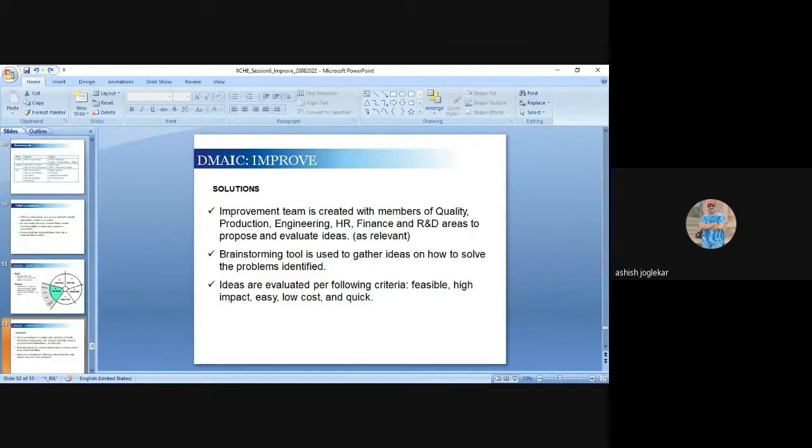Once the management has approved, you again call all the people who are working in all these functions, train them on the new system, and give them the new SOP in writing. If you are going to change something, give it to them in writing, train them, and then declare that we are going to do this pilot from this day to this day, say 15 days. Then ask somebody to take data for the 15 days. You are doing the pilot, somebody has to take data. What is the time required? Has the production improved or not? Whatever may be the result. In that 15 days, you do the pilot, take data, and wait 15 days. Don't hurry up.